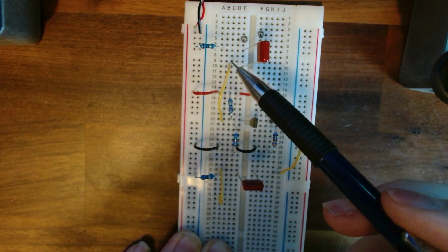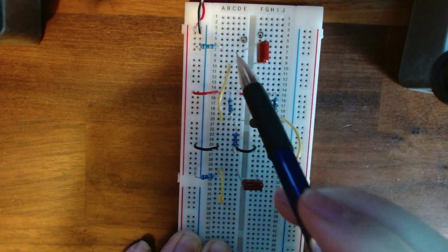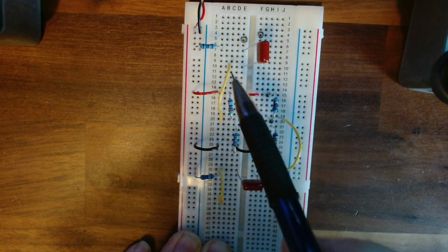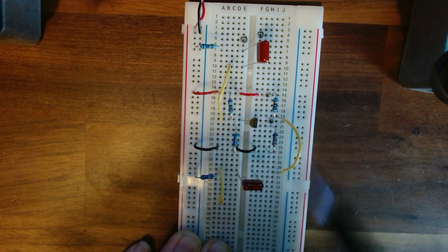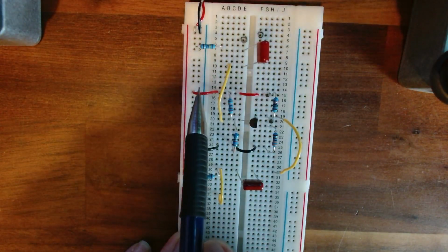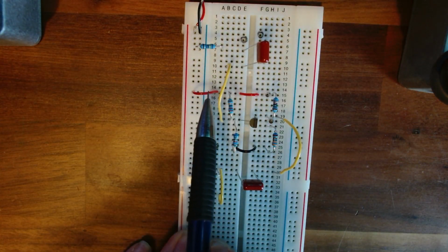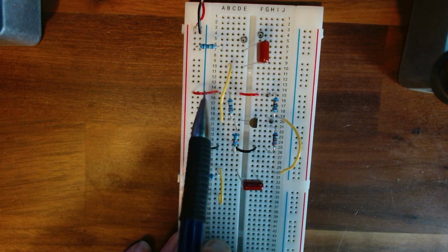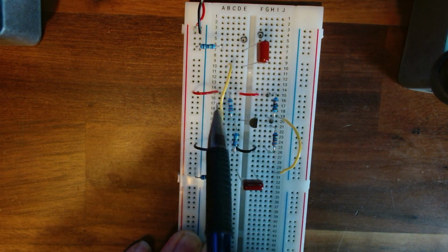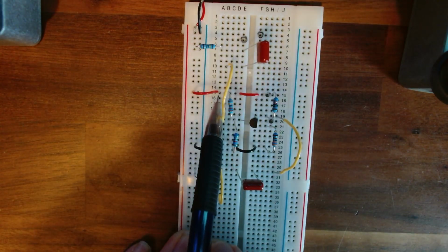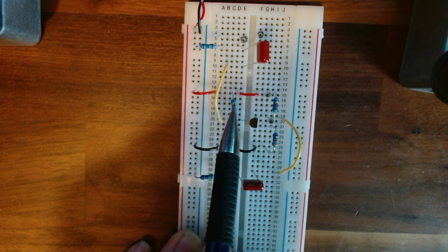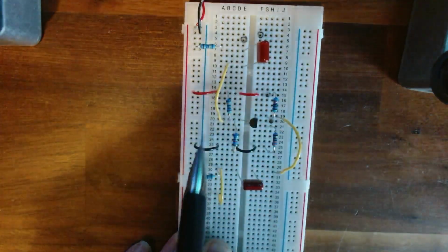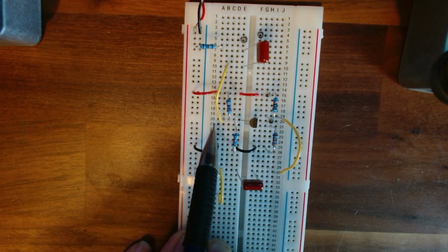Later on, when we connect this circuit up, we'll put a line here on pin 7 out to our input. It'll go through this capacitor, through this line, and into the base of our transistor. I use a red line here for our power. It's going into line 15 here. It's covered up by the wire, but it's pin 15 here. And then we've got our 220k resistor going from line 15 and joining line 20.